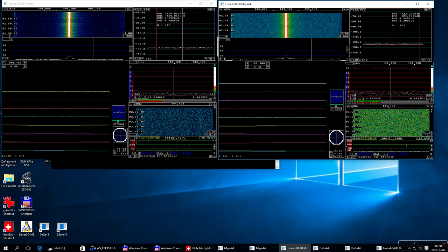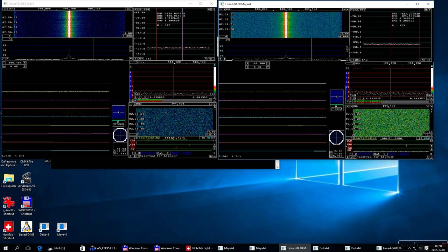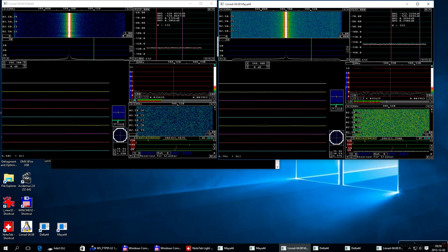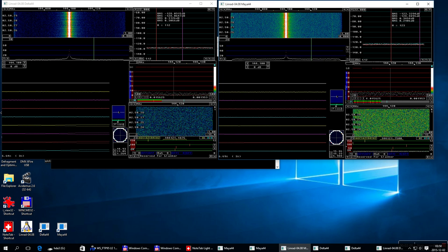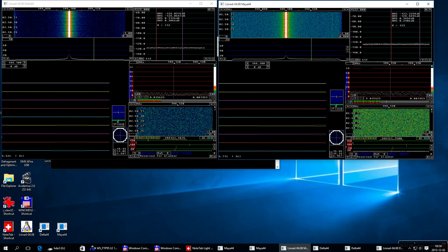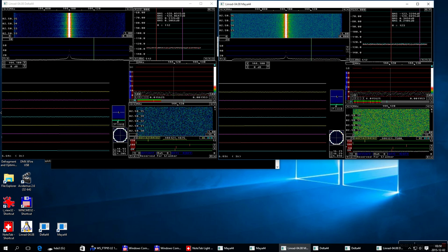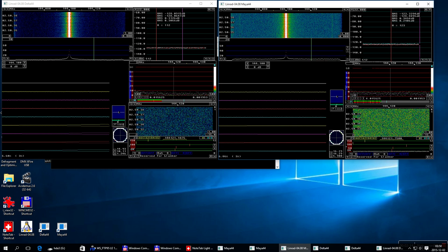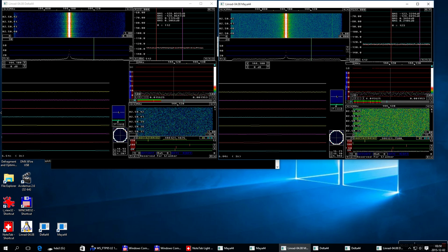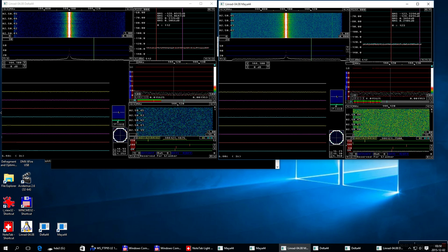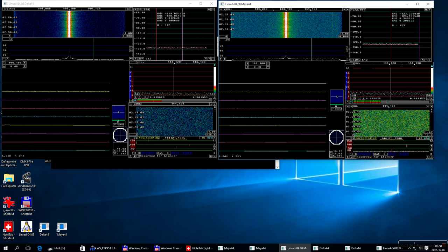This means that the noise figure at the input of the IQ Plus is 5 dB better with the Delta44 than with the Maya44. Now this Delta44 card is modified, so it's a little bit better than the original design. You can read about that on my homepage. But even an unmodified Delta44 is a bit better than the Maya44.